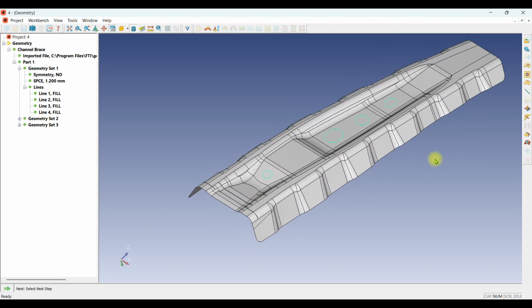How to do that? We have in here what is called double attach. So double attach comes with 2 options, mirror double attach and advanced double attach. So if you want to create a symmetrical part, you can use mirror double attach. Meanwhile, if you want to create a non-symmetrical part, for example, in here we have a right hand and in here we have a left hand, we can use this one, advanced double attach. So in this case, we're going to use mirror double attach.